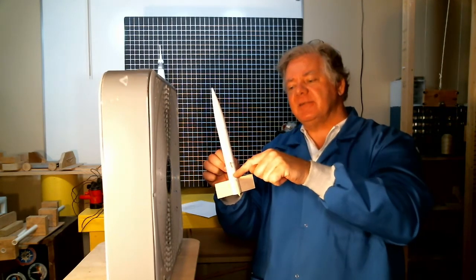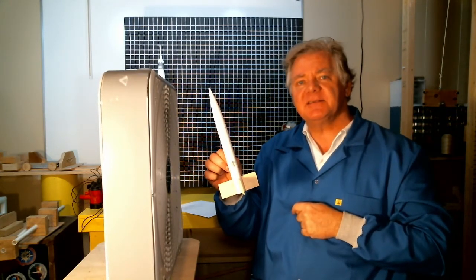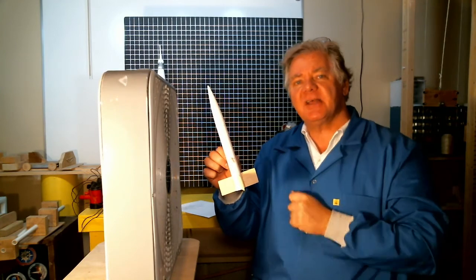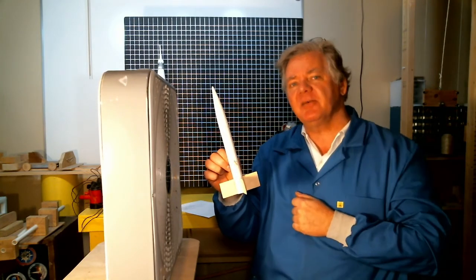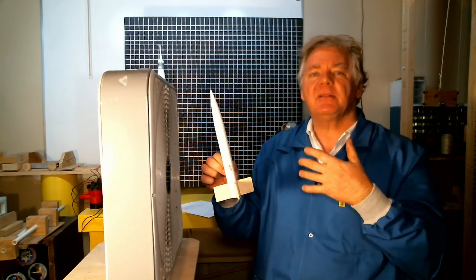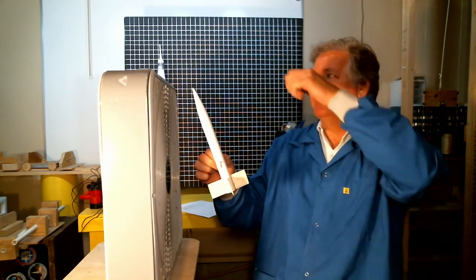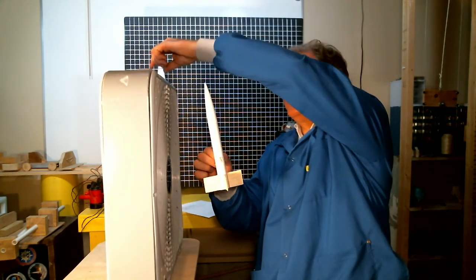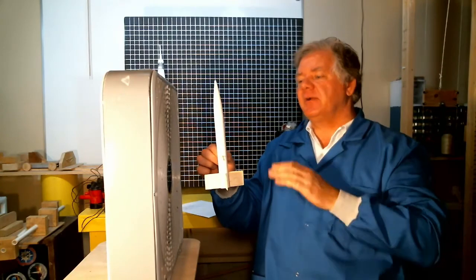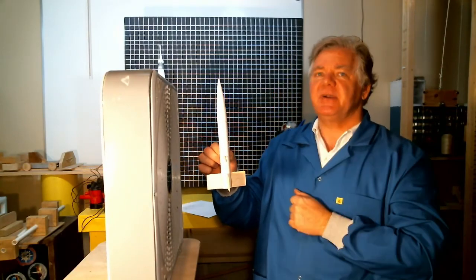And that's due to the aerodynamic forces acting on the fins, creating a moment around the center of gravity of the rocket, causing it to pitch into the wind. Now, a rocket with a large static margin or a large stability will tend to pitch more than a rocket with a smaller stability. Again, turn off the wind, and the rocket will tend to pitch straight up again.